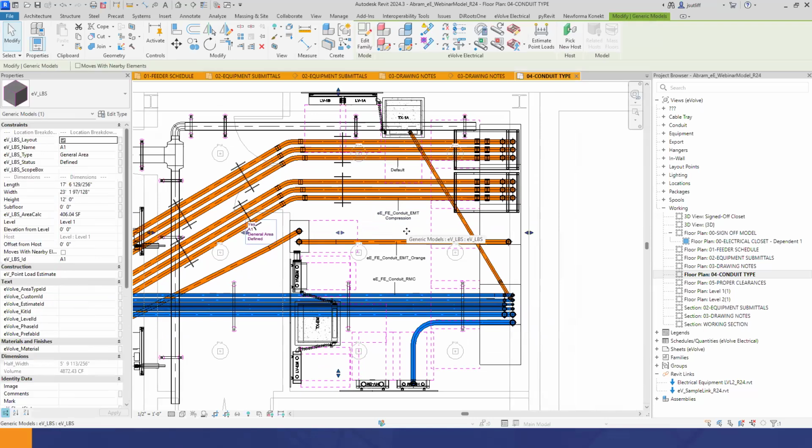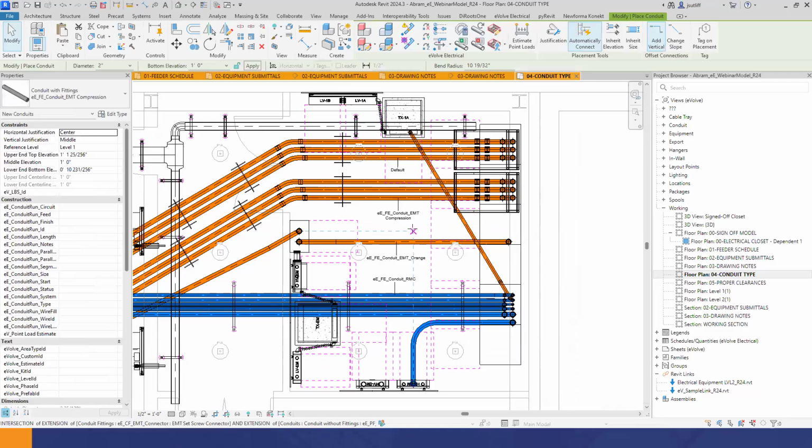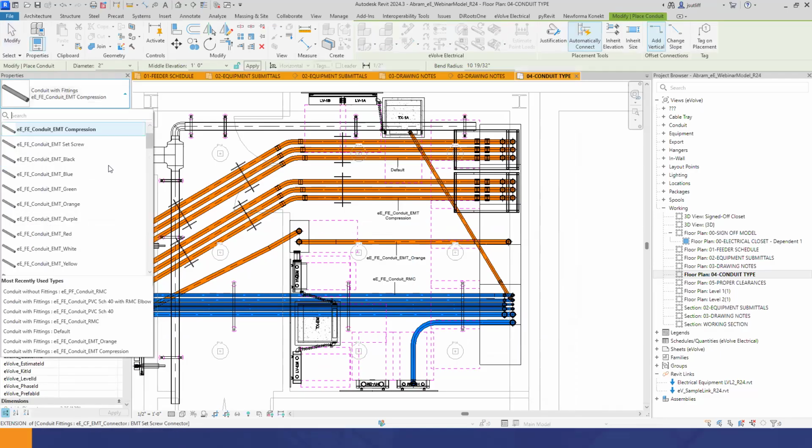And like I said, I've done this because I hit my keyboard shortcut and I didn't change the type of conduit that I was utilizing, modeled an entire rack system, did parallel conduit runs, and then realized, crap. Now I got to go through, highlight all, change it all, make sure the elbows are correct. Is my spacing correct? Did that change anything downstream? You can see it snowballs.